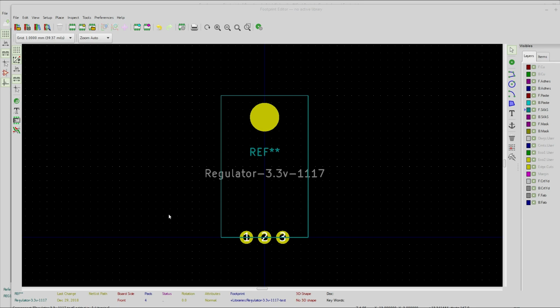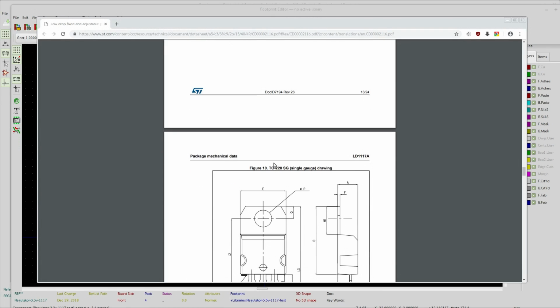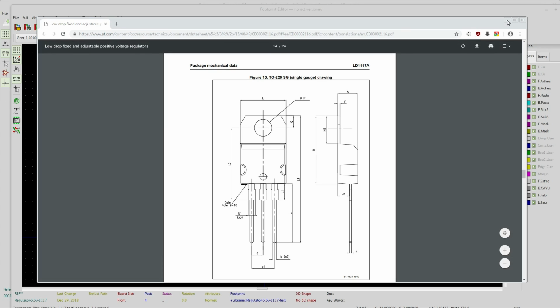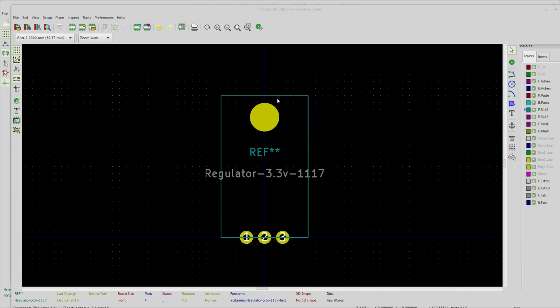When we have all of this going on here, and this potential slight amount of randomness as far as where this thing gets bent and where this hole ends up being lined up, and now the possibility that the PCB manufacturers might not drill the holes exactly in the right spot, it's not going to be way off. But putting that all together, you want to build some extra tolerance into all of your stuff.